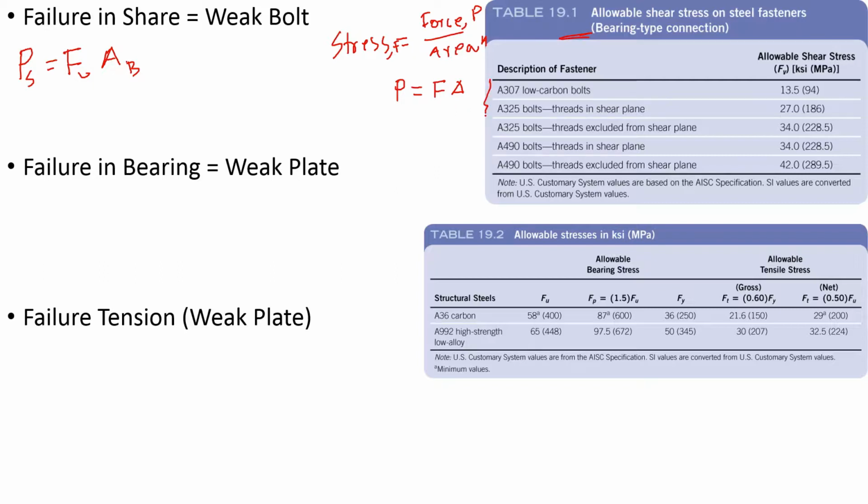Depending on what type of bolt that is, we can have the allowable stress for that type of bolt. So that is already found. Now, if we have a total of capital N number of bolts in the connection, then this total load will be more. Now, if you have a total of small n number of planes in the connection, for example, in a butt joint you have 2 planes, in a lap joint you have only 1 plane. So this is the number of planes, this is the total number of bolts in the connection, this is the cross section area of the bolt, this is the allowable load.